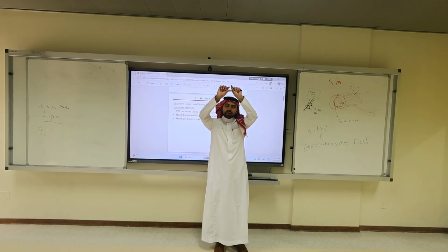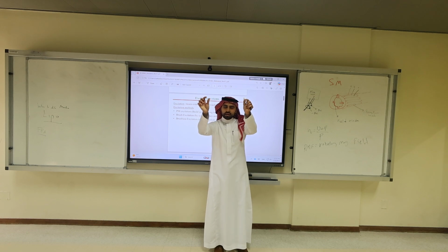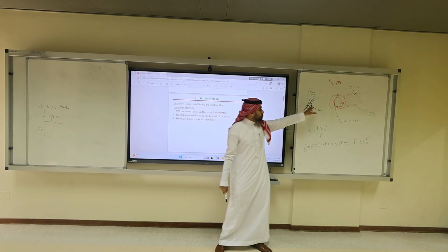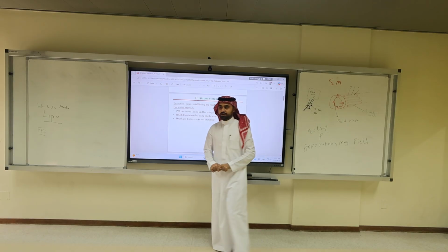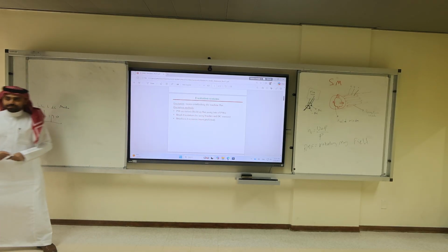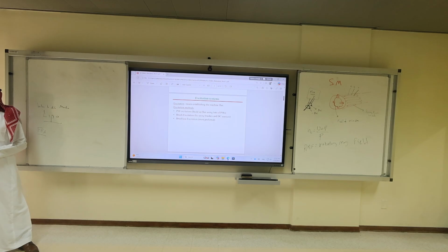The slip rings are a 180 degree ring, and then there is a space, and another 180 degree ring. They rotate with the shaft. Half of the time you connect to positive, half of the time you connect to negative. They're mechanical devices. Any question about them?